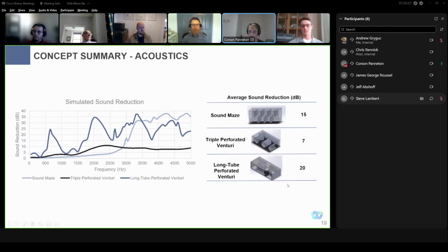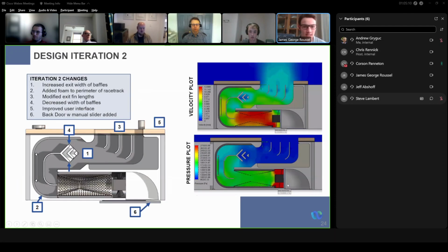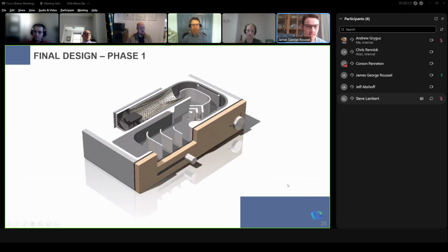Yeah, sure. We actually did end up doing a bit of a filter, at least. This design we have right here was our first prototype that we built. We started with a 60 millimeter fan, and it was quite noisy to get the amount of airflow that we wanted. So we ended up switching to an 80 millimeter fan, and with that we could really reduce the sound the fan was producing, because in ambient conditions you could really hear that fan. But now that we've transitioned to the 80 millimeter, in ambient you barely even hear this thing.